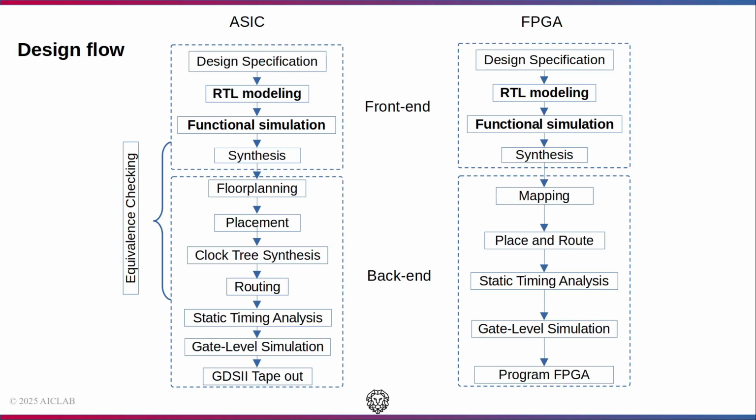Logic equivalence check or LEC is a formal verification technique used to mathematically determine if two different representations of digital logic are functionally equivalent. For example, the RTL code and the synthesized gate level netlist are the same.